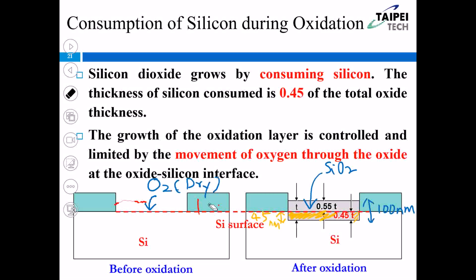So which material can we use? Actually, we use silicon nitride because it's a very hot material, a very strong material, okay? Do you still remember when we mentioned the silicon nitride? We know it's a very hard material with a high hardness, right? So, can I put the silicon nitride on top of the silicon directly? Silicon is soft.